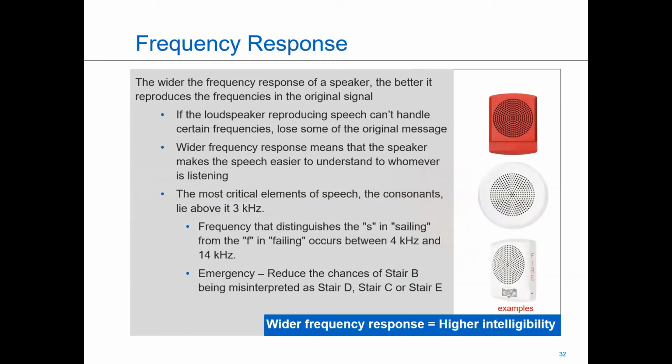The wider the frequency response, the better it's going to reproduce the frequencies of that signal. Some of them are required. We're talking about intelligibility right now of the speaker. Some of the speakers would need to be not only registered or certified or compliant for specific applications, but a speaker needs to be compliant with that frequency response to be able to reproduce the sound. Something in the fire world that's changed in the last few years was the low frequency sounder.